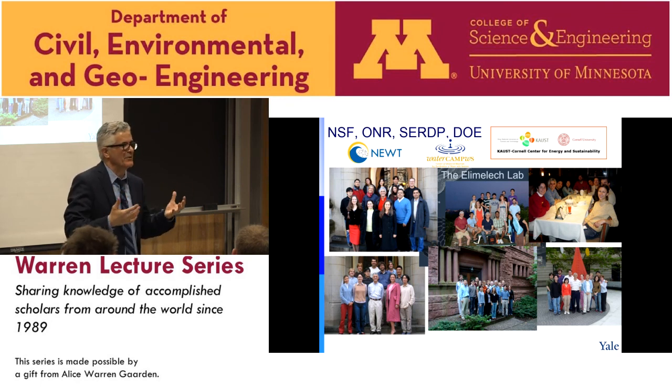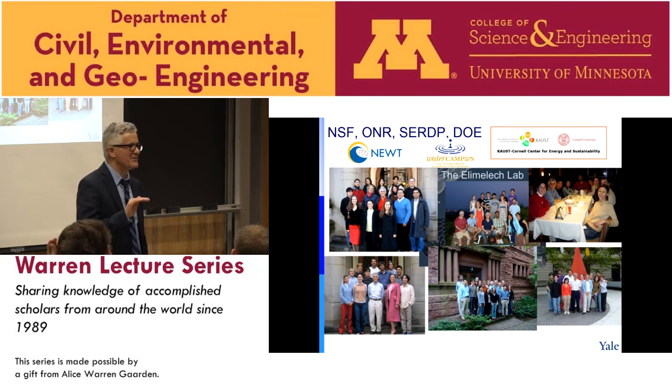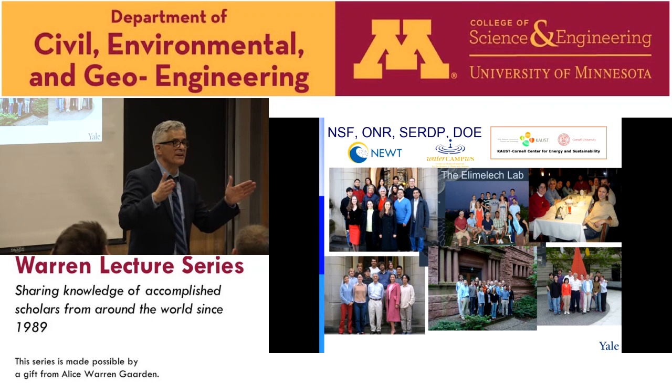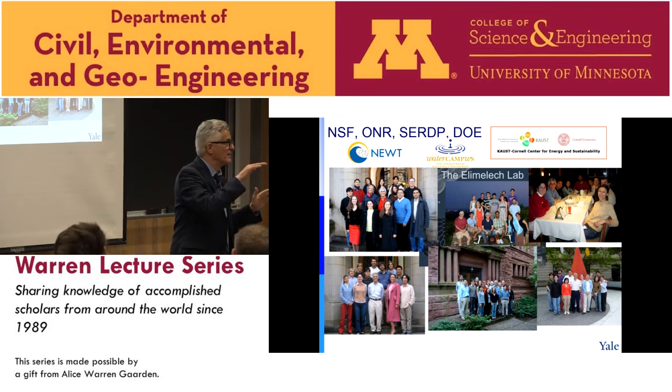They already built it in a way that they can adjust it the way you want. I guess I'm asking more whether increased permeability, you're saying, is not going to change energy, but that could change production versus unit time. Good question. I did not want to jump into it. If you have high water permeability, you're right, you will need much less membrane area. Now, membranes are only 4% of the total cost of desalination.